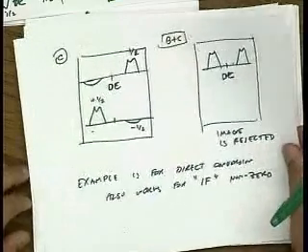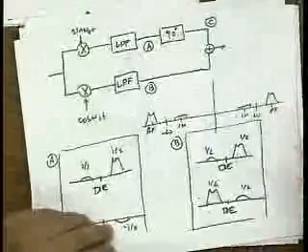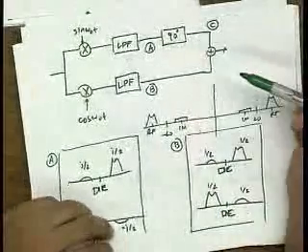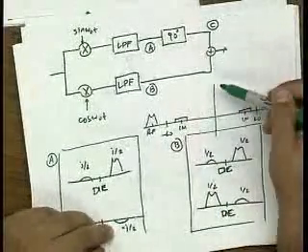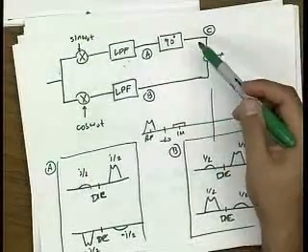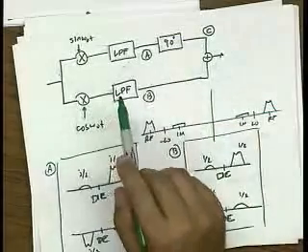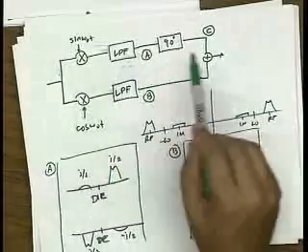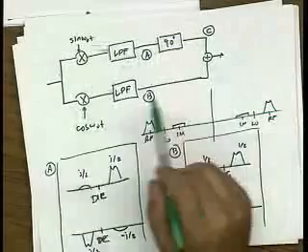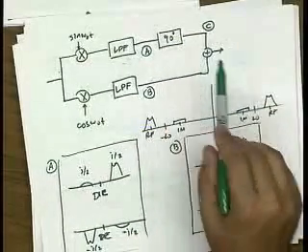Well, if you go back and look at this architecture and you do this analysis, since we have a cancellation that occurs, it's very sensitive to the gain in each path and the phase in each path. So here, mathematically, it was easy to say that the gain is plus 1/2 or minus 1/2, or phase is exactly 90 degrees or minus 90 degrees.